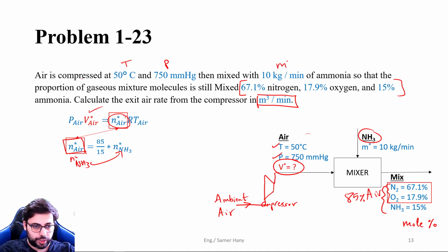All right. And of course, just a quick comment here. We're using the ideal gas law with the dot notation since this is not a static container that just contains some volume in it and that's it. We have a mixer and we have streamlines, these ducts or pipes that transfer the gases. And we can also describe the gases by the ideal gas law, but this time we'll take into account that they are flow rates and not just static values or a static system. So it's like we just divided the entire equation by the time.